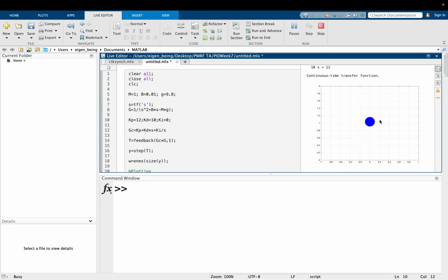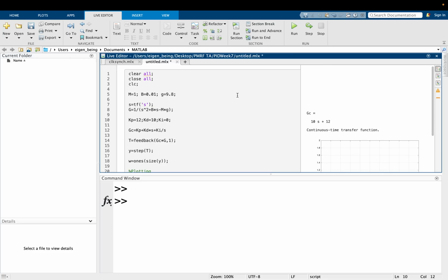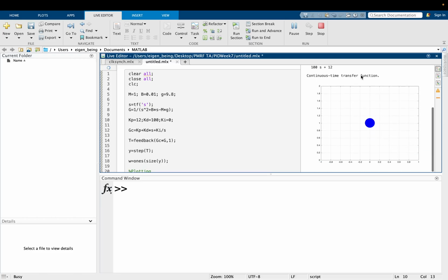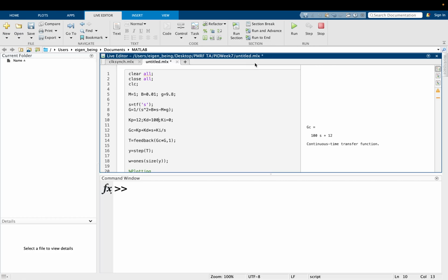Okay, now this looks promising. So okay, it's going, but why is it going there? It's slowing down and going somewhere. So I'll just increase my damping. I'm just arbitrarily increasing; I'm not doing any analysis based on what damping it should be. So this is highly damped now. So maybe I'll not increase this much. I'll just increase to some 50.